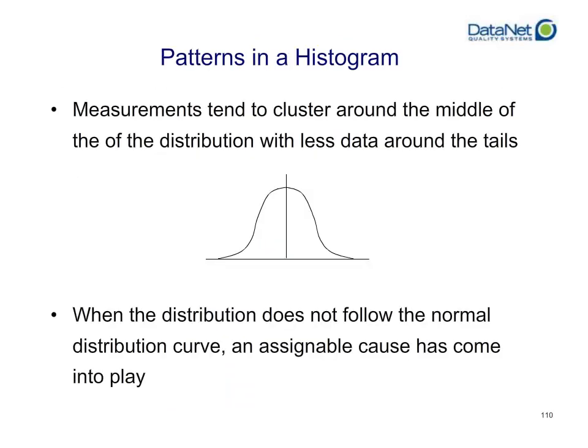Now with a control chart, what you see is how your data is doing in real time relative to how the data was behaving historically. So even one subgroup that is outside of control limits is going to be a cause for investigation. With histograms, once you have that data and you want to analyze the actual data and put it into a histogram, you can actually find patterns within the histogram and learn from that.